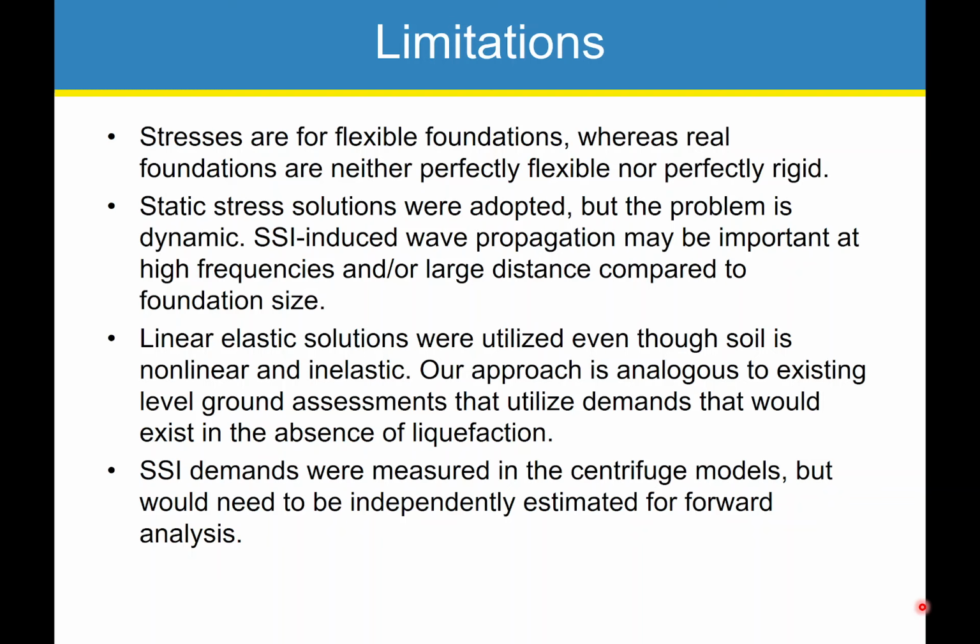We use linear elastic solutions, even though the soil is nonlinear and inelastic. We're actually trying to predict whether it will fail, so obviously it's a nonlinear problem. We would just argue that our approach is analogous to existing level ground assessments where we use demands that would exist in the absence of liquefaction. So maybe elastic solutions are not all that bad. For the most part, they're independent of modulus. They just are equilibrium considerations.